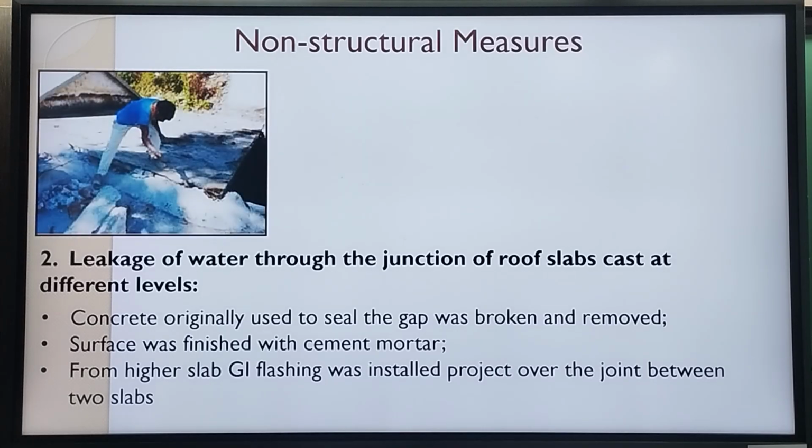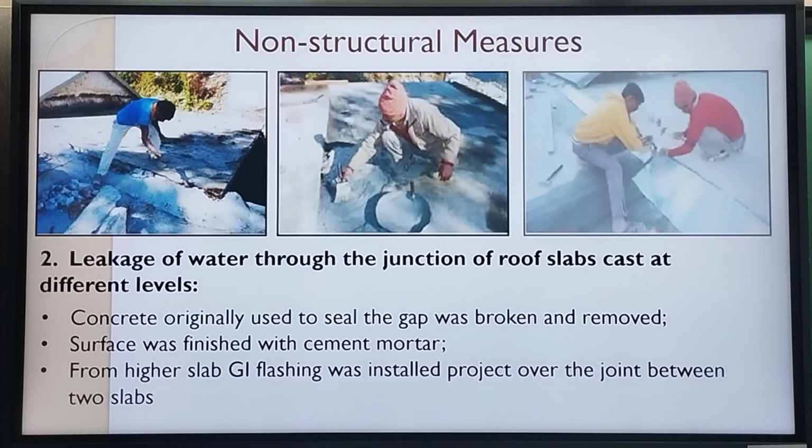Then the leakage is here. Alright, see, this was an interesting situation where we had this slab. That's the old building. This is the new slab which was put in later on. And then came this. This particular room slab is lower than here. But what they had done was put a lot of concrete here, thinking that this would prevent the water from leaking in. But a crack developed here and water started going down below.